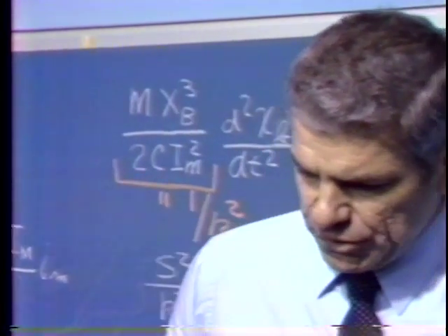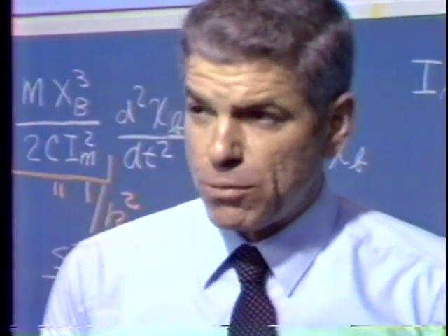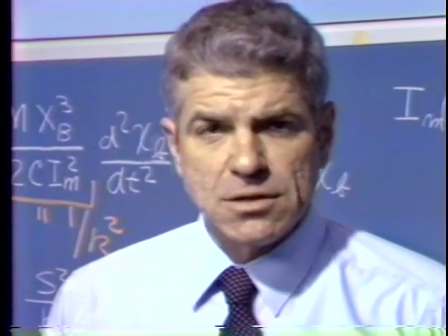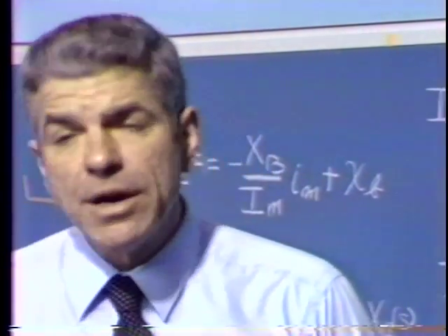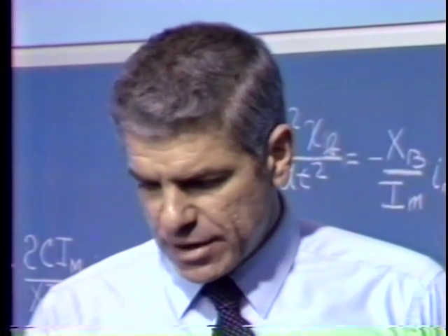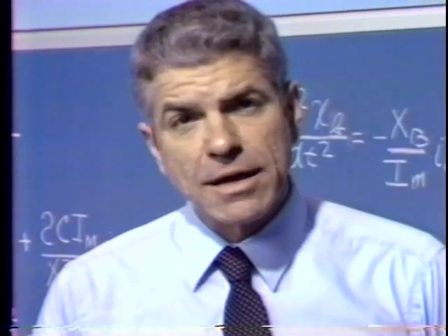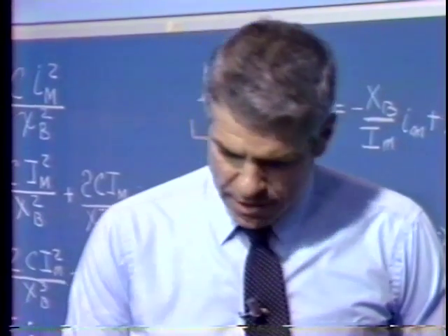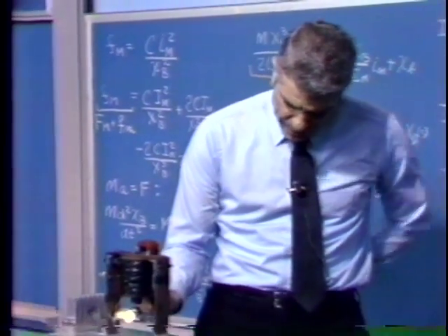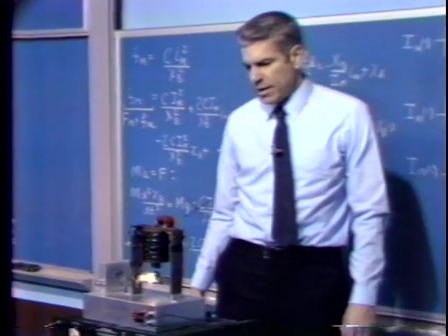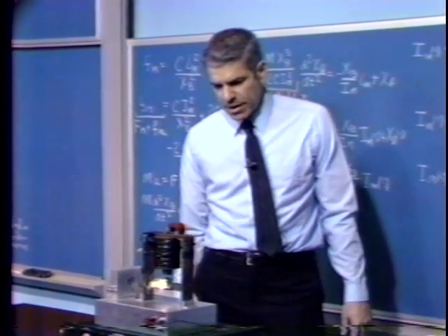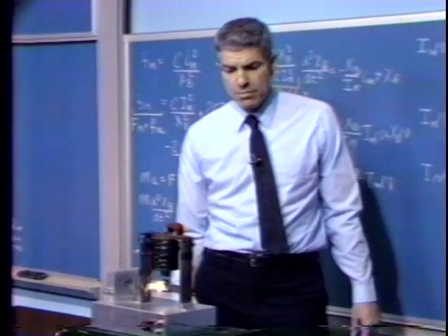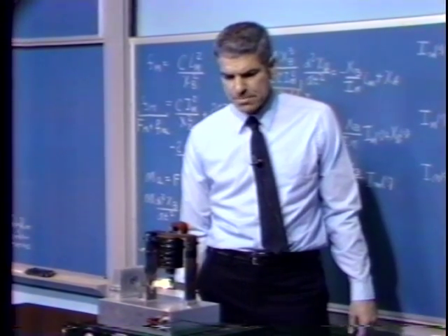And that was the approach used, so that way they effectively supported the spinning wheel in a magnetic field, in effect a frictionless support, without having to put any power into the electromagnet. Yet they still retain the ability to modulate the magnetic field in order to stabilize the system. It's a rather interesting extension of this idea. And again, we've seen that the ball, when started spinning, will continue for a very long period of time, demonstrating the very nearly frictionless nature of the support provided by that sort of magnetic suspension system.